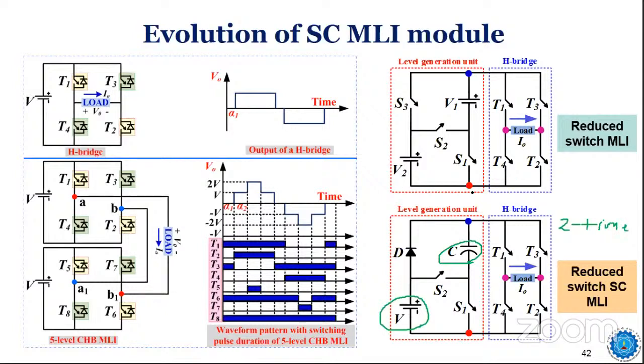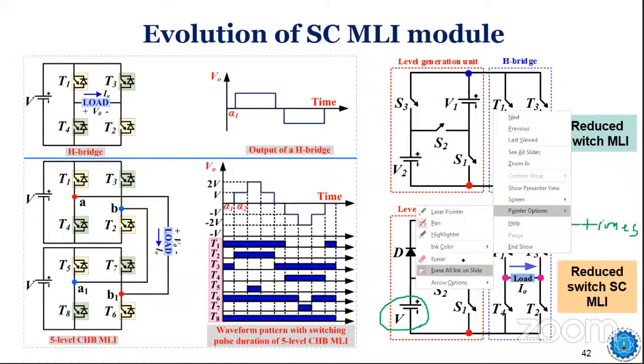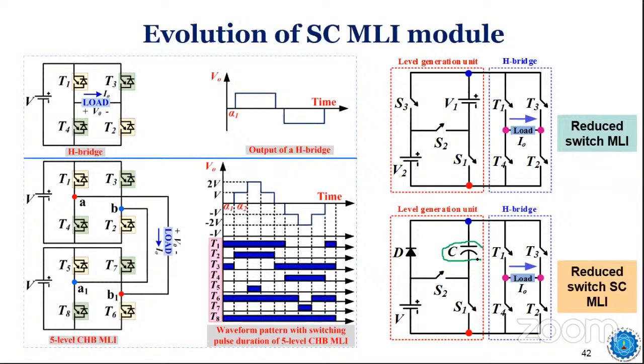That is the first feature. The second interesting feature is that, when you connect a capacitor, you need to think about how to regulate the capacitor voltage, whether you need an additional sensor or an additional controller. No, you do not need anything here, because in parallel it is initially charged, current is flowing. In series, it is discharging.